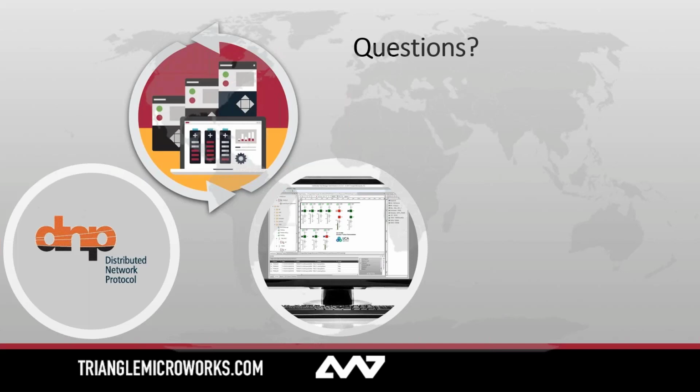Yeah, so we have a built-in protocol analyzer, and what you can do is open this protocol analyzer and actually see what values DTM is sending and receiving. It's all scope-based, so if you do it on a folder, you're going to see all the protocol traffic going in and out of the devices in that folder. If you do it at the top-level workspace, you're going to see everything that workspace is generating. That way you can log that information, export it, and have access to all of the protocol traffic that you're seeing during your tests.